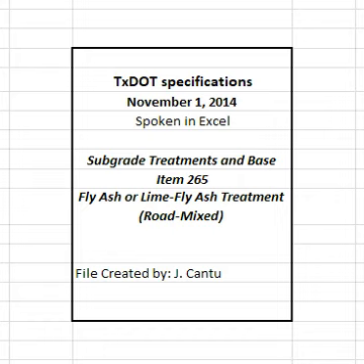When material is imported from a borrow source, notify the engineer of the location of the borrow source well in advance to allow time for testing and approval to avoid delay to the project. Stockpile as directed. The engineer will test the borrow source and determine the sulfate and organic contents. When the borrow source has a sulfate content greater than 3000 ppm or an organic content greater than 1%, proceed as directed. When new base material is required to be mixed with existing base, deliver, place, and spread the new material in the required amount per station.